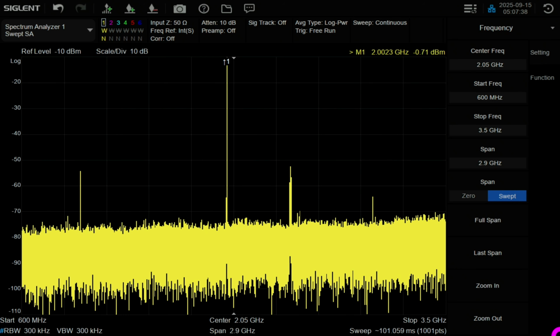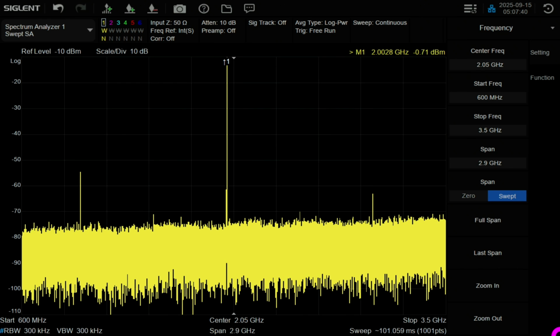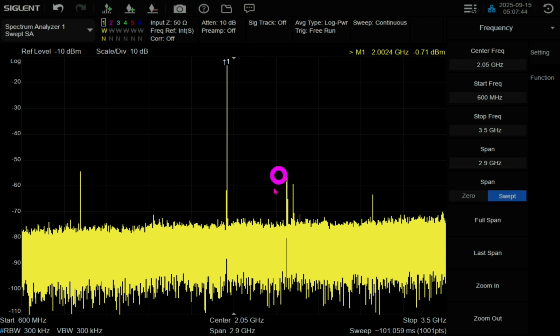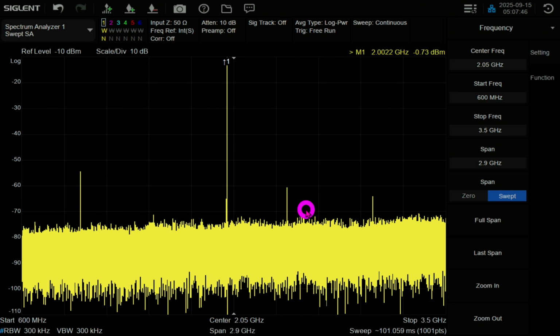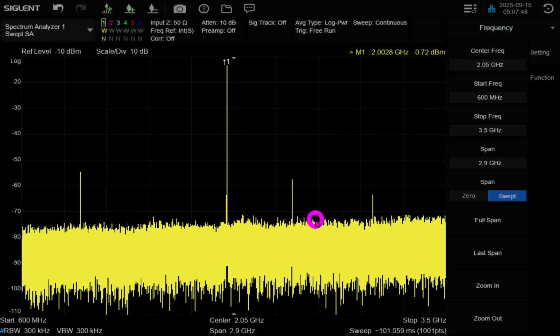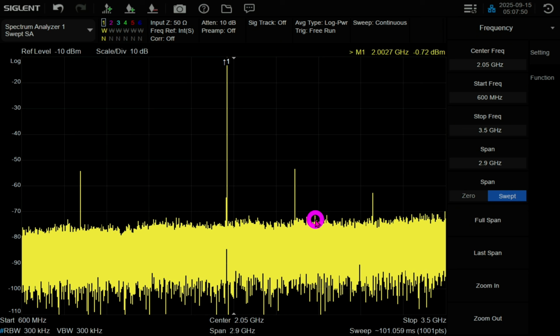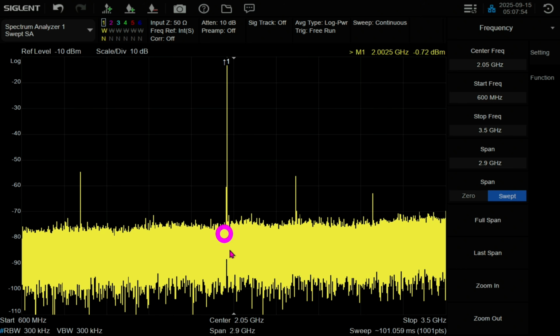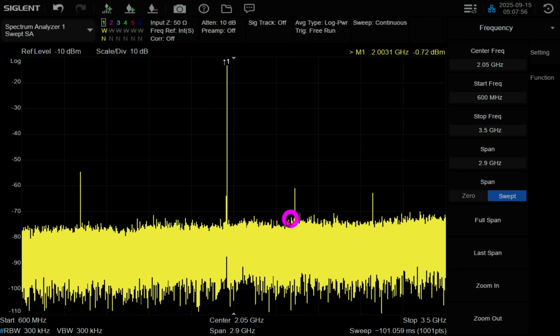So I went ahead and I changed the frequency of the instrument to actually 2 gigahertz rather than 2.5 because it was too close to all the Wi-Fi and Bluetooth activity that you can see around here. The reason all that couples to the output is because, of course, there's no cover anymore. The instrument is completely open and it's a huge antenna, so it's going to pick up all kinds of garbage and it's going to interfere with what we want to measure. So that's why I moved it a little bit further down.